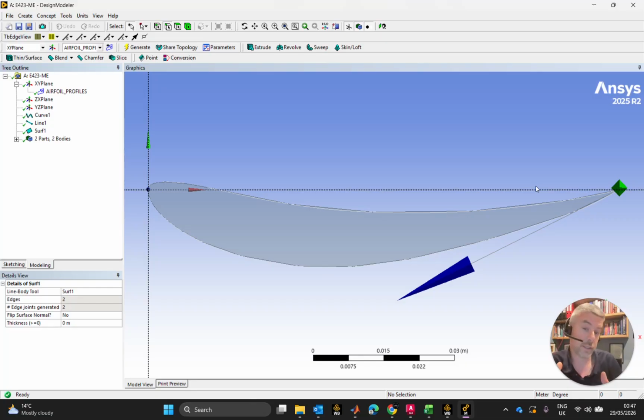Do I want to make it 600mm? Well, if I make it 600mm, I could leave a 100mm gap, 4-inch gap there. That's not bad. Now, the other regulation would state that the trailing edge of the wing cannot be more than 250mm, or well, any part of the wing cannot be more than 250mm above the track as well.